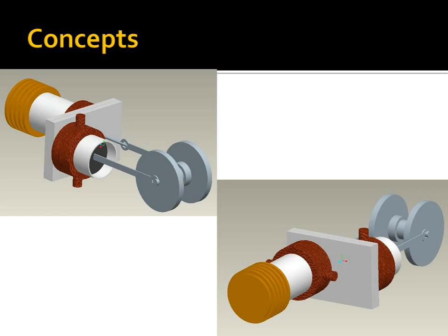It incorporates a brass heater cap for increased surface area and improved thermal conductivity through the displacer cylinder wall. It incorporates a stainless steel displacer cylinder and power cylinder. It incorporates two copper jackets for lowering the temperature of the cold temperature source. An aluminium power piston, more than likely. I'm still looking at data and research into the material suitable for a displacer piston.